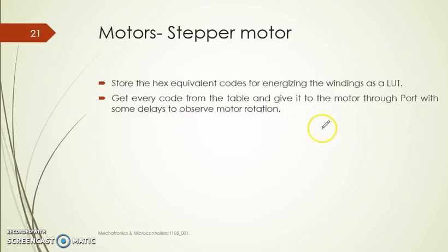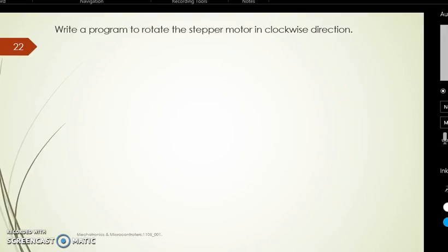One important point to note over here is that the stepper motor cannot be directly connected to 8051 in case it is having high current demands. So in that case we require a motor driver circuit and then you interface the stepper motor to it.